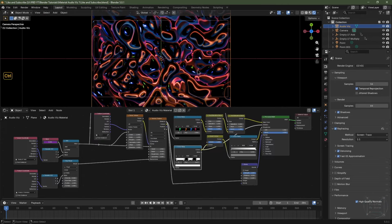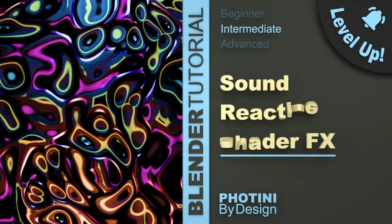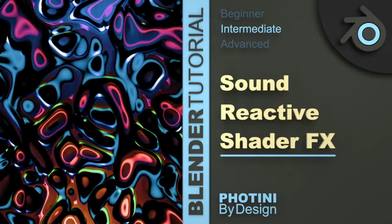I'll then hit Ctrl S to save the project, and then it's simply a case of hitting Ctrl F12 and that will render out your image sequence. From there you take the image sequence and the audio into a video editor and then render it out as a video.